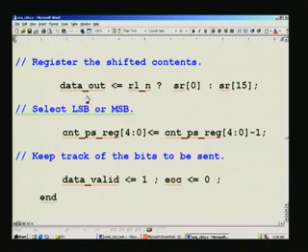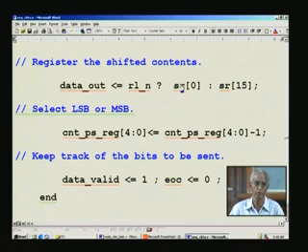This is for actually registering as such. What we have seen is a shift register used internally, that does not come out as such. So, the output you have to route to the actual data out, and that is what we do once again based upon the right or left shift here. If it is right shift, what we have to do is assign SR[0], because when you right shift, the LSB will be sent out first. That is what is being done here.